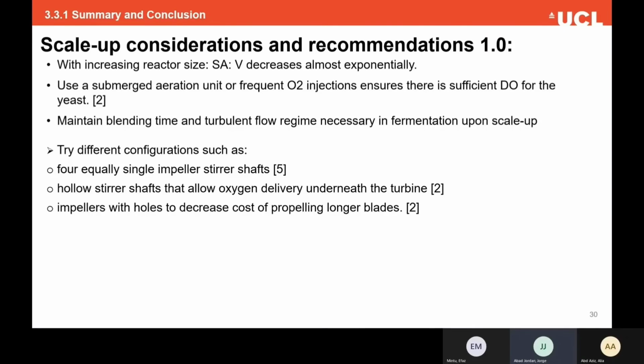Furthermore, there is an inverse relationship between mixing time and power consumption, so we must account for the considerable trade-off. Therefore, it is ideal that we chose to use a double configuration with a high-speed Rushton impeller and a lowest-speed, power-consuming pitched turbine at the top.